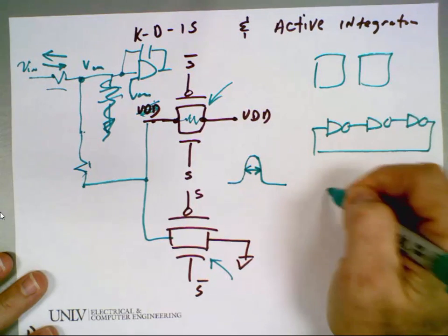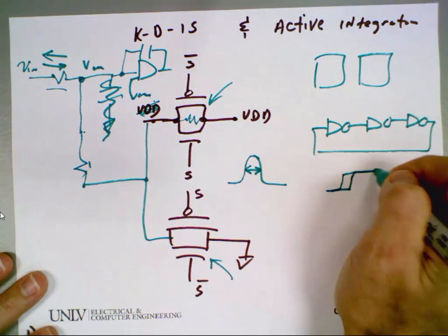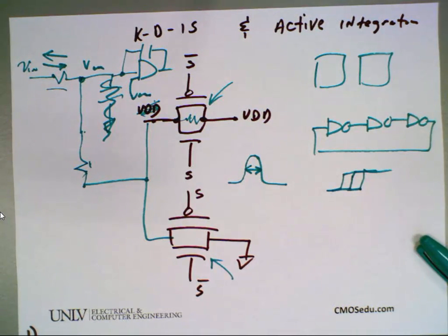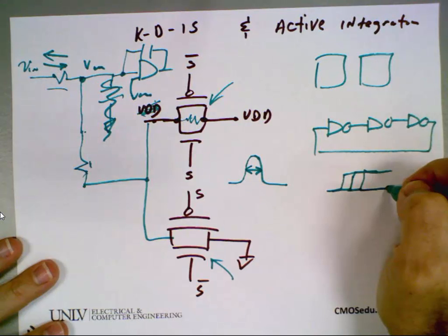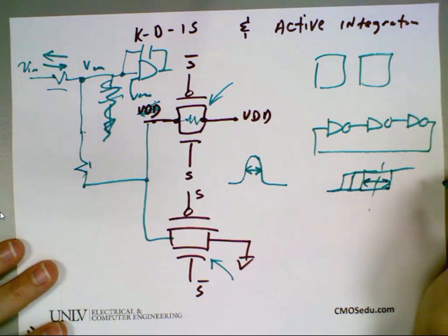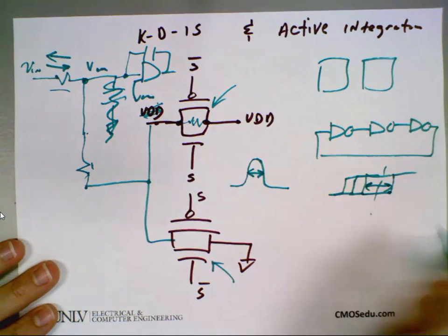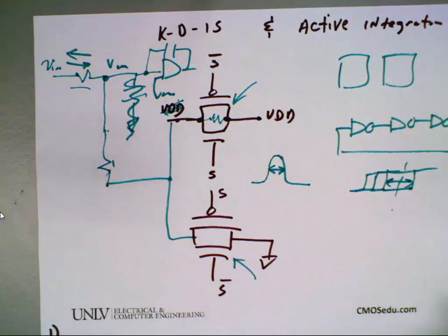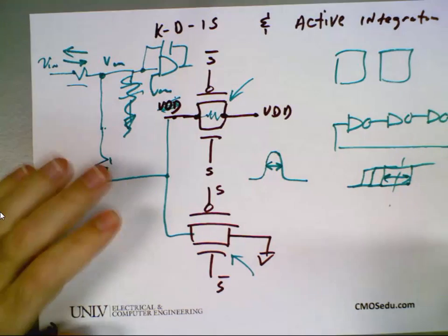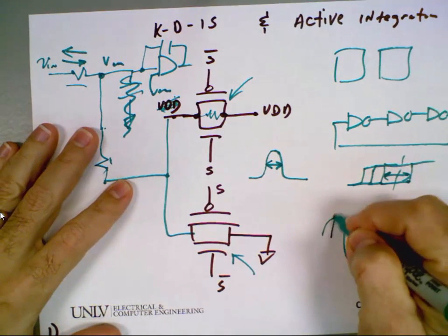The problem is if your edges aren't evenly spaced, you can get the effects of clock jitter. So you say, okay, I've got 8 edges, and the final one I'm just going to ignore. Well, you have this big clock jitter issue here, right? And the problem with that is you'll get amplitude modulation in your output. You'll see when you do the project. Your output will be reconstructed, and then you'll look at it, and here will be your input, nice and flat, and your output will be going like this.